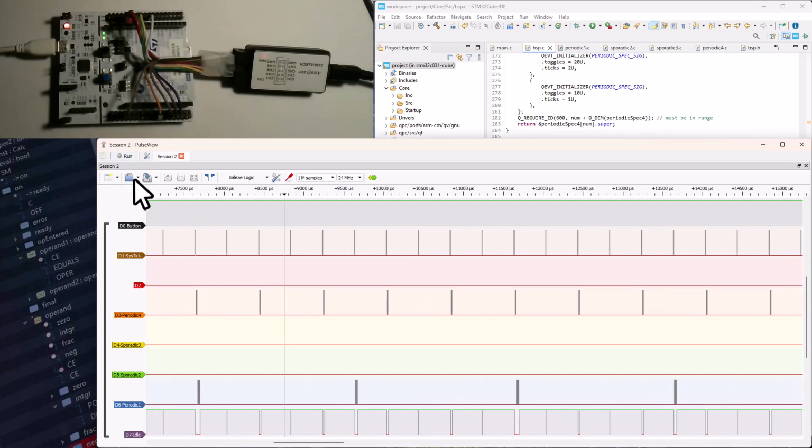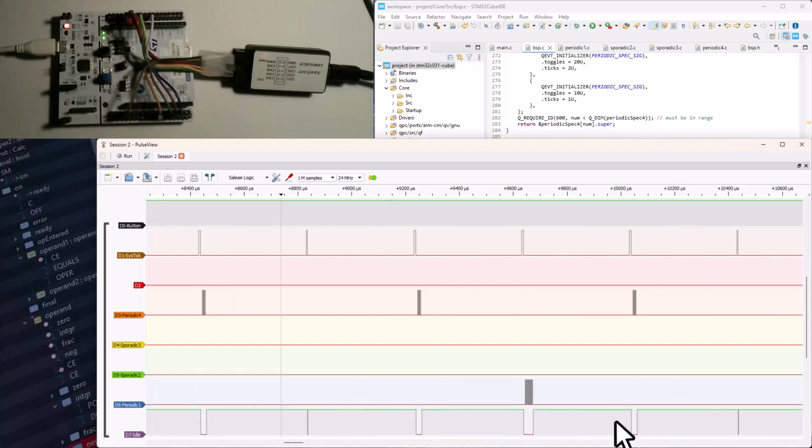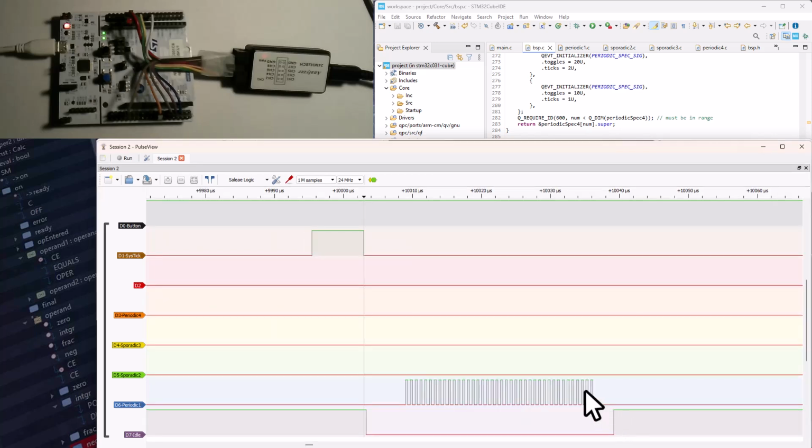As you can see, the idle trace is not toggling anymore, meaning that the QV_onIdle function is called much less frequently, thus not wasting as many CPU cycles. Moreover, most of the time the line is high, meaning that the system is inside the QV_onIdle function. Also, the interrupts preempt the superloop inside the QV_onIdle function, and the function returns only after the interrupt. Then the system processes the posted event and calls QV_onIdle again.